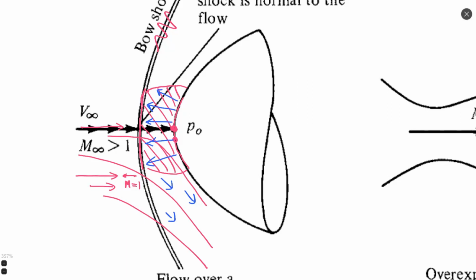Question from Ian. What do we know about the flow properties inside the shock wave? Very nice question. We do not know anything about flow properties inside the shock wave, because the thickness of a shock wave is equivalent to the free path of molecules. So theoretically, Anderson says that we cannot see a medium inside a shock wave. There is no medium. There is just one transition, one energy transformation. There is nothing of flow inside.